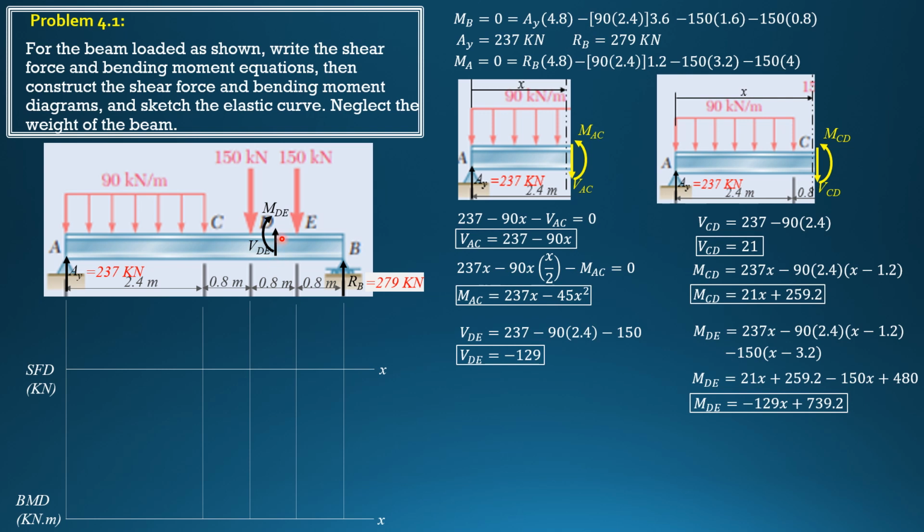So the positive sign convention, shear DE is upward and moment DE is downward, is clockwise this time. And for shear, the positive shear DE therefore is downward minus upward, because if we consider the left portion, it was upward minus downward. So that's the shortcut. If you're still confused, then you just set up the equation summation of forces in y equals 0.